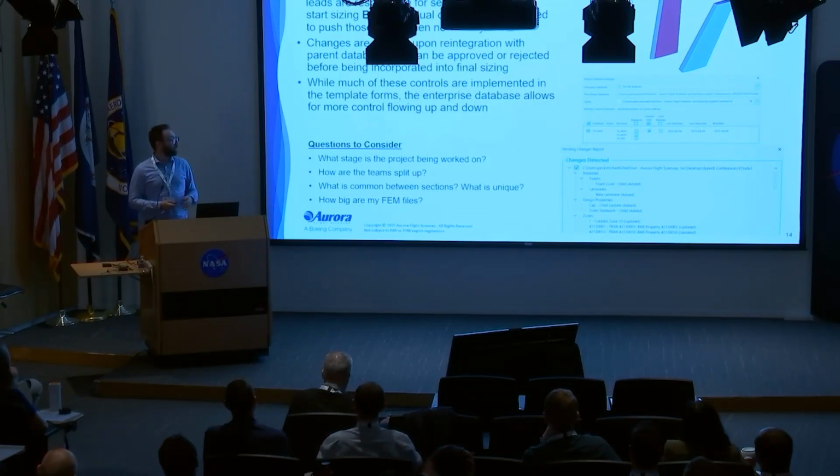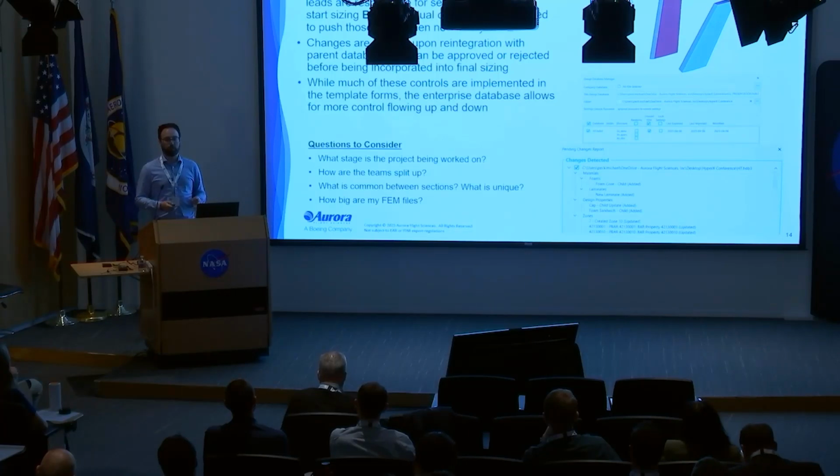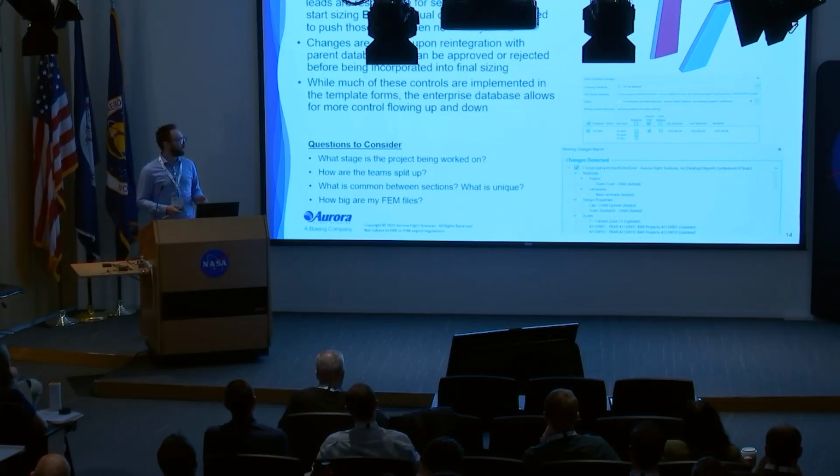And then you do have to take the reality of what the size of your cases is. For a GFEM, are we talking about a 30,000 element or grid GFEM? Are we talking about a 100,000 grid GFEM? And how many load cases? If you ask some older stress engineers, they want like 10 load cases in your size on a wing. Some people say no, 2,000 load cases.